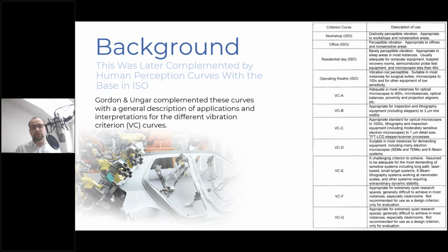Now, please take a look at VCG to VCE. These are very challenging criteria to achieve. Already when we're talking about VC curves, something that needs to be stated because I know that we have a mixed audience: when we talk about VC curves, we're talking about vibration levels that are so low that you can't really feel them. We're no longer talking about vibration levels that can be a threat to the structural integrity of a building or a bridge. We're not talking about vibrations that will have a negative effect on the human being if he lives in an area with that kind of vibration, such as VDV. We're talking about vibration levels that are to be applied on the most sensitive equipment.